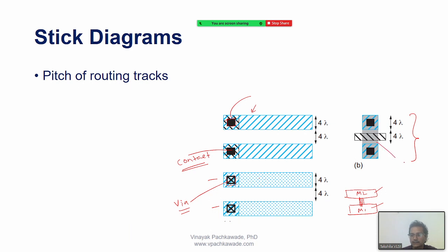Gray area is diffusion. Okay, what is this shaded? It means I have drawn the metal overlapping with this diffusion, and there is a contact. It means there is already a contact metal making contact with the diffusion area. This could be source or drain. Another here, again a metal, I am making contact with the source or drain.